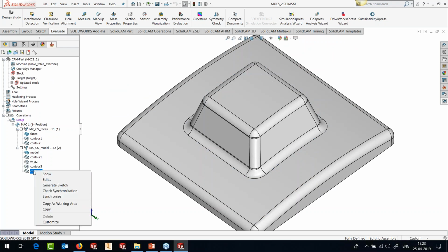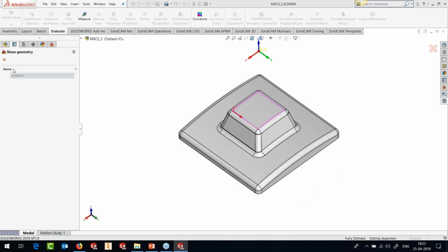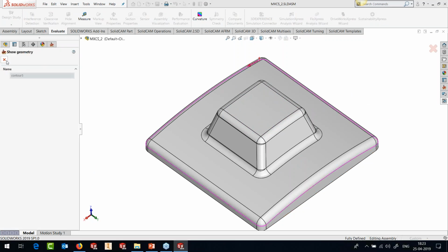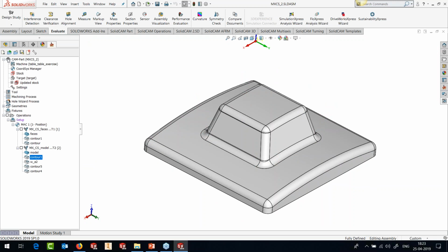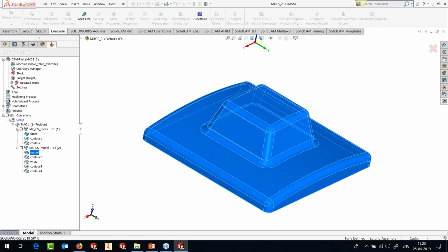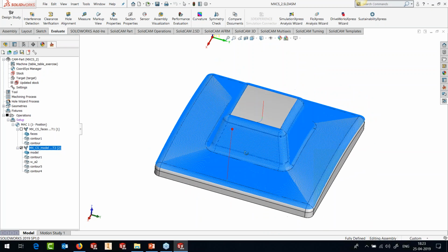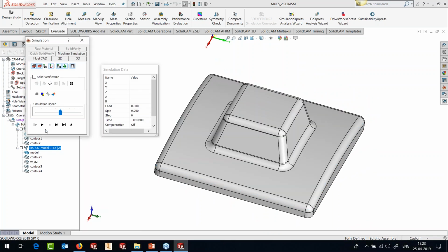The other method is out here where we have two curves. One is the inner curve here, this one, and one is the outer curve, that's this one. On top of that, I have got a boundary that I've defined. And of course, the tilt lines. So what do I get with my multi-axis constant step over? In this case, I have not used faces, but I've said directly machine this entire mesh that is being provided. So if I look at the toolpath, this is how the toolpath comes up. Constant step over right from the start till the end.